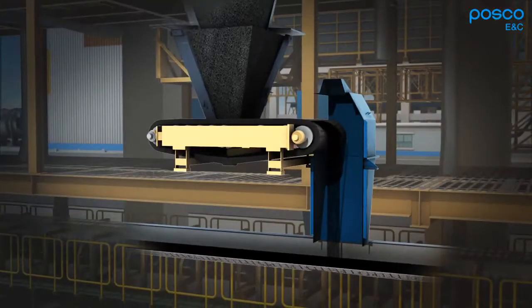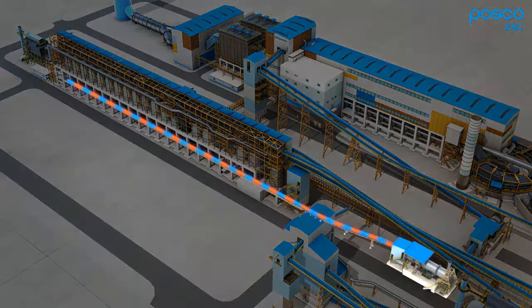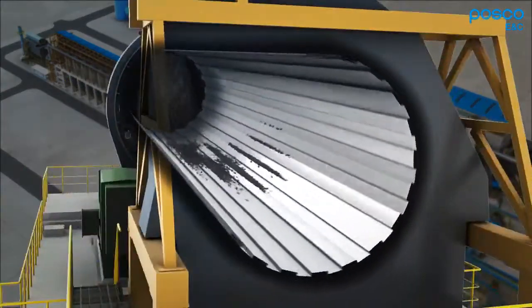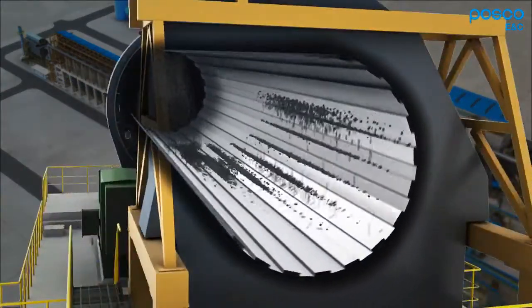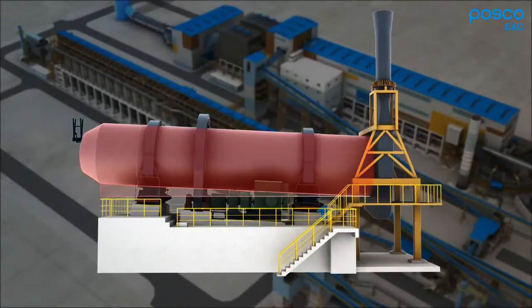The raw materials and fuel, discharged at a proper ratio, are transferred to mixing drum by the belt conveyor. The mixing drum mixes each raw material evenly, adding moisture. The rotation speed and angle of the mixing drum are designed at an optimal angle for mixing the raw materials.